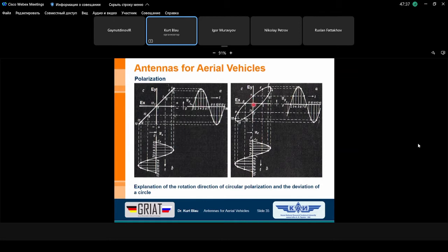Both dipoles are driven with the same voltage, the same magnitude, but now we change the phase angle between the voltages. Yeah, and then we can see here, let's start, for instance, at time 0 with this voltage. We are here. The other voltage has at time 0 a negative magnitude. And so our starting point is here with the outgoing E field component. And now we proceed, we go here to point 2, also laying on this axis. We also go to point 2.